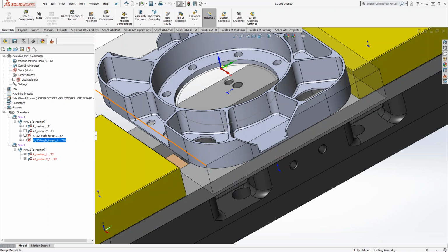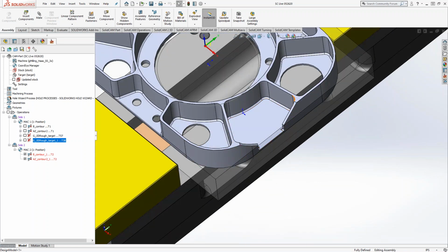Now, if you don't have the Pro package, 2.5D Pro or 3D Pro, and you just have the standard packages, then this could be done with a series of pockets. Using the Smart Face feature, you can actually just click on the bottom faces of each of these pockets and then get it to automatically recognize geometry for you and get a very similar functionality, except here you would have to add the step down, the step over, and the feeds and speeds, whereas iMachining will provide that for you for optimization of the toolpath.